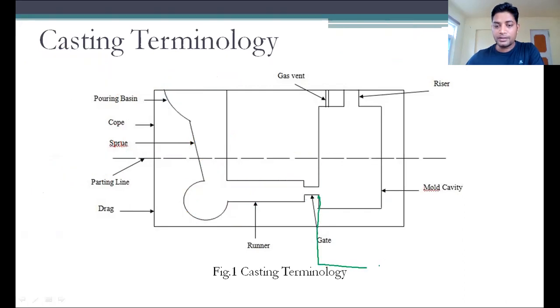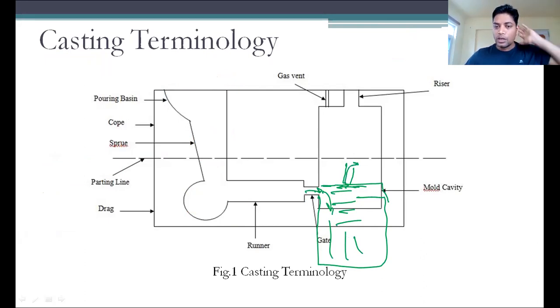the mold cavity like this, right? We have to create the mold cavity like this. So the molten material we are pouring will first fall like this and fill, okay. And if this is filled completely, the molten material comes from this area, this riser we can say. But we cannot keep it like this, okay. The reason is that here the molten material will fall, and if it falls, then definitely there will be turbulence, okay. Turbulence, because it is at a very high temperature, it's not water at atmospheric temperature, it is at a very high temperature.